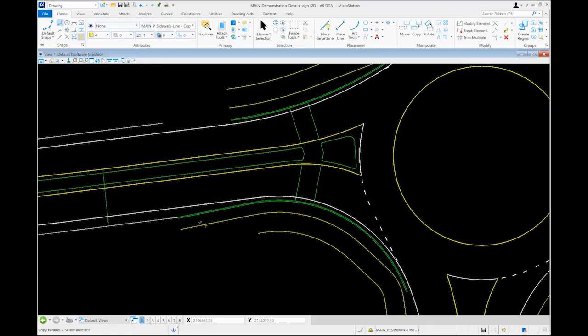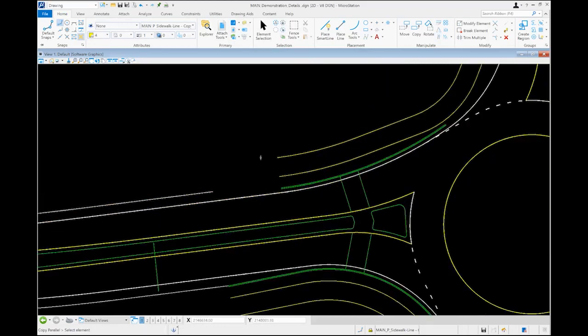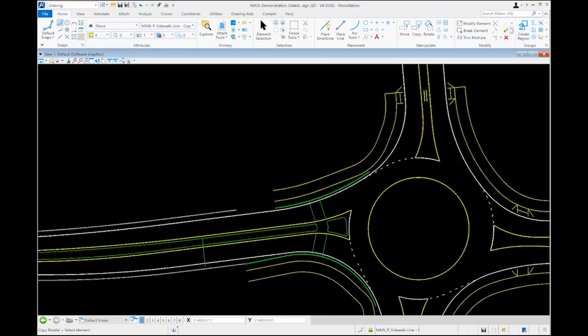So if I continue to carry this 10 foot, now these will end up getting carried further down and ultimately transitioning into our roadside sidewalk that would be along the outside. The distance here is going to vary depending upon our drainage needs. And so ultimately, as this sidewalk continues along this facility, this distance will really be dictated by what's needed for the roadside swale and the associated roadside topography. So we're just going to push that out there for now.